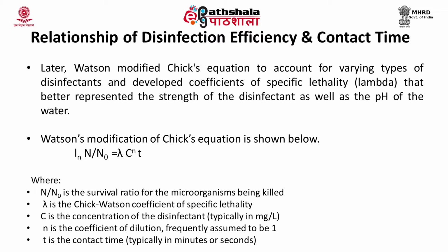pH of the water. The equation is: log value of the survival ratio of the microorganisms is equal to the specific lethality coefficient lambda multiplied by the contact time and the concentration of the disinfectant.